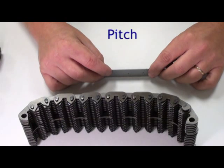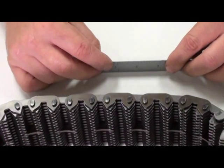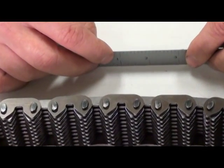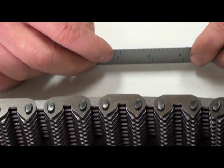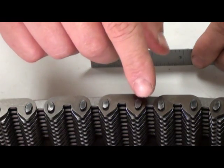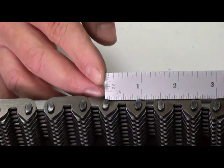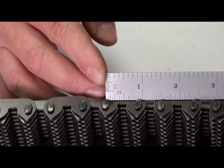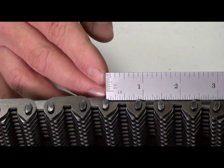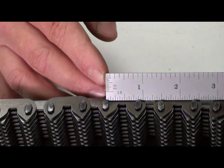There are a number of ways to measure chain pitch. The simplest method, which will work for both single pin and two pin silent chains, is to measure the distance between the center of 3 consecutive pin heads and divide that number by 2. For example, the distance between the center of 3 consecutive pin heads on the sample chain is 1.5 inches. Divide that number by 2. We determine the pitch to be 0.75 or 3/4 of an inch.